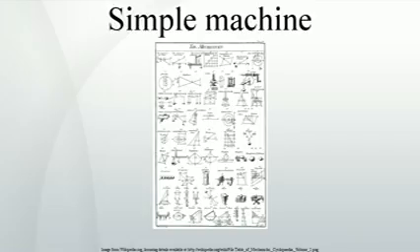If the simple machine does not dissipate or absorb energy, then its mechanical advantage can be calculated from the machine's geometry. For example, the mechanical advantage of a lever is equal to the ratio of its lever arms. A simple machine with no friction or elasticity is often called an ideal machine.